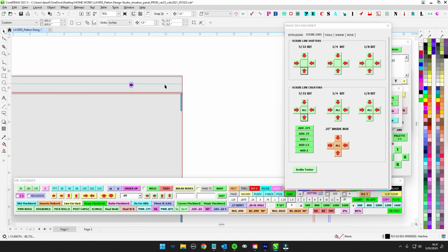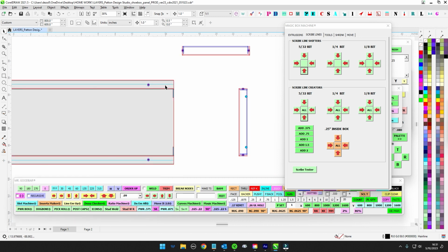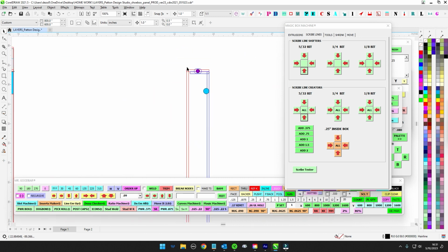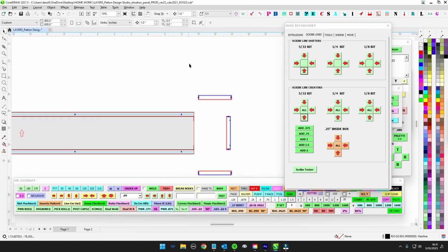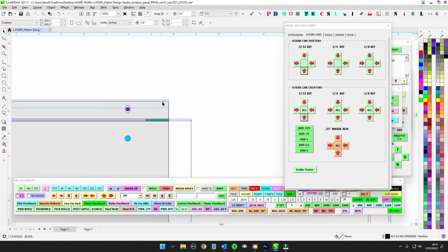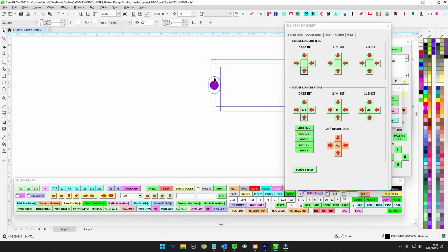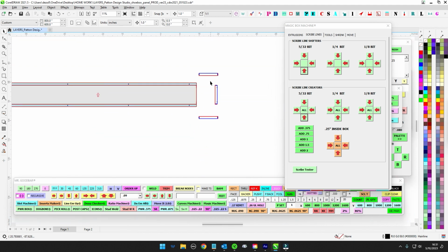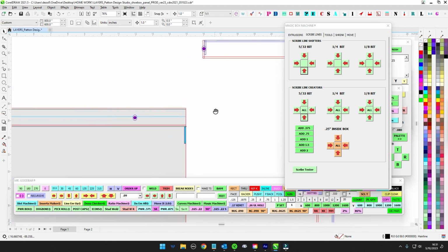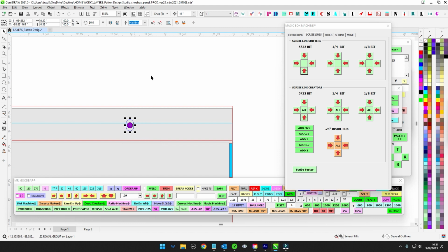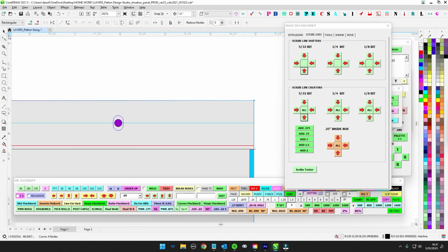And so now we are adjusted, and when the guys clamp and bend, it will be the true size. But again, when it comes to the face, the backer we have to adjust because it literally won't fit. But the face has that luxury: if all it's going to do is grow a 1/16, then leave it. If that's the case, you do not have to shift these. If you're going to leave this at a 1/16, then you don't need to shift the hardware because you want this to remain a 1/2 inch.